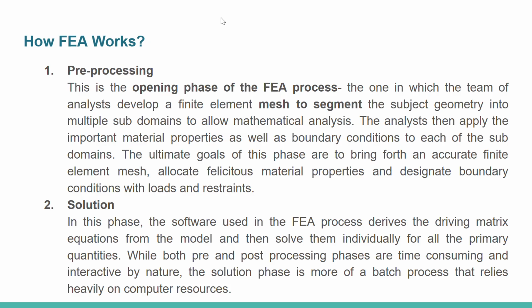Second is solution. In this phase, the software used in the FEA process derives the governing matrix equation from the model and solves them individually for all primary quantities. While both pre- and post-processing phases are time consuming and interactive by nature, the solution phase is more of a batch process that relies heavily on computer resources.